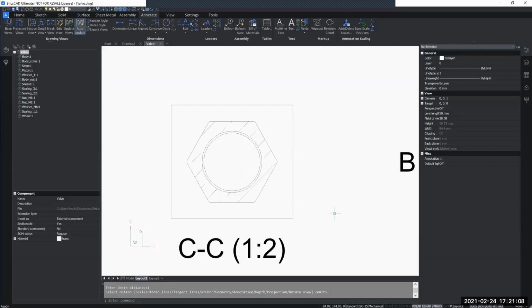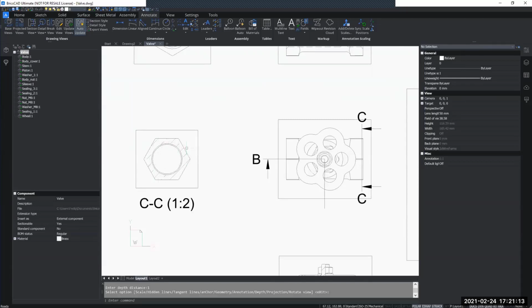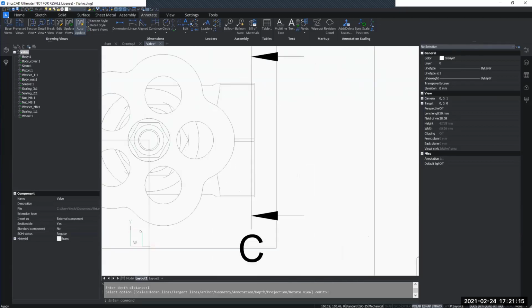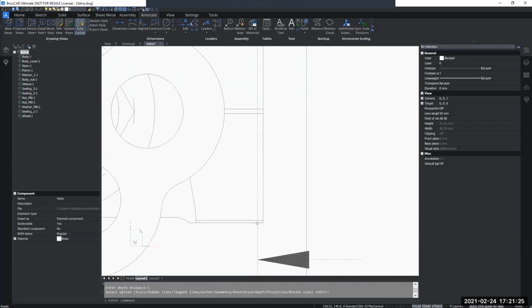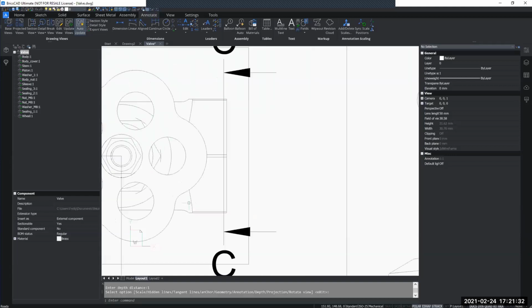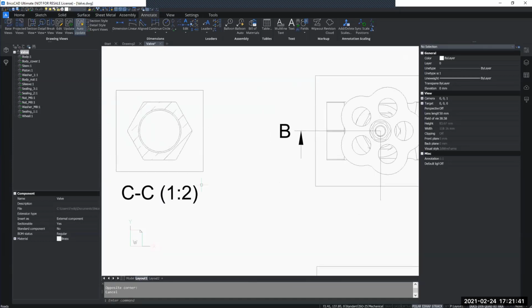past my section line. So the way it works, it is that the face we see here is the section line, and all of the material it keeps is only that 1 millimeter extra that I typed in. So it keeps the section line and then a 1 millimeter slab past that section line, and everything past that it disregards in that view. So everything past here, for example, is disregarded as it's not interesting in this specific view.